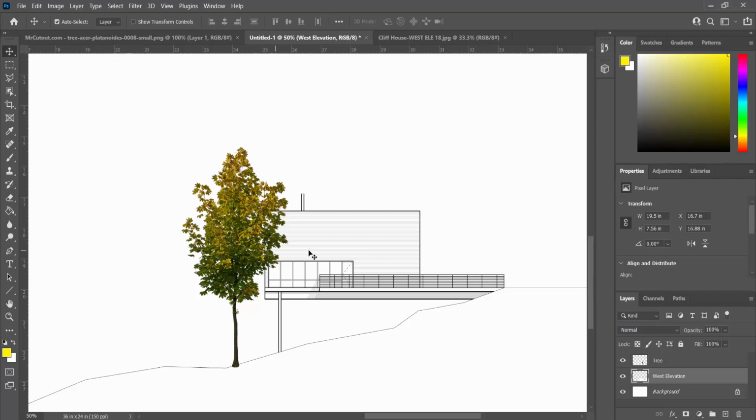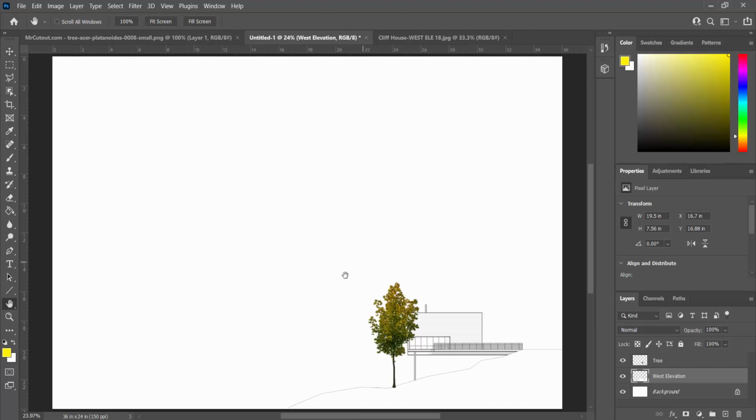So obviously, if I look at this as an image, double clicking the hand zooms in everything. If I want that elevation drawing to be somewhat dominant here, I know that that green yellowish color, while pretty, is definitely overriding my ability to see that elevation. So I want to desaturate this. Essentially, I'm going to turn it black and white and then fade it out, put it in the background, and then I want it to show up behind this house as well. So I'm also going to duplicate that layer. Well, let's desaturate it first so I don't have to do that twice.